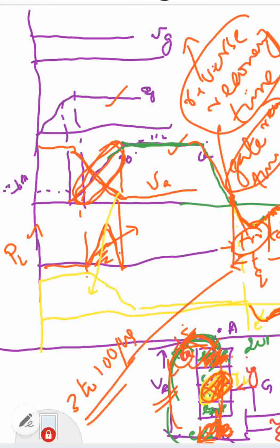That's the meaning. Okay, so the conclusion of the switching characteristics is that SCR will not turn on instantaneously. It will take 1 to 4 microseconds to turn on. Similarly, SCR will not turn off immediately. It will take 3 to 100 microseconds. Okay, the total turn on time is divided into 3 intervals: delay time, rise time and spread time. Similarly, the total turn off time is divided into 2 intervals. One is called TRR, reverse recovery time, and TGR. TRR means outer layers are recovered, TGR means inner layers are recovered. Why this negative voltage appears here and all these things you will learn when you learn about the inductive circuit in the second module.